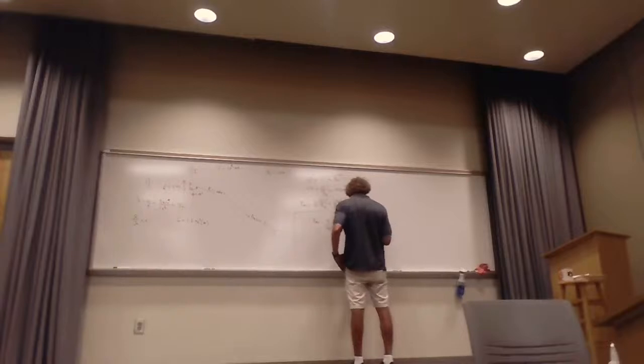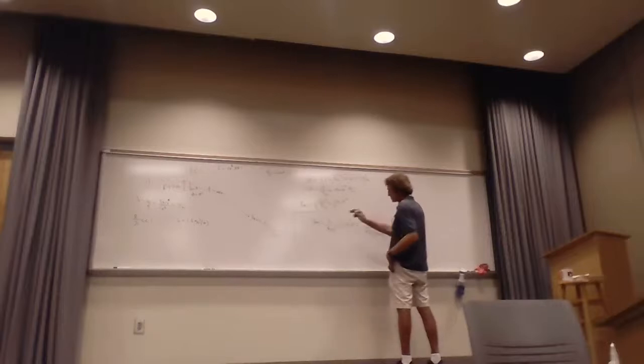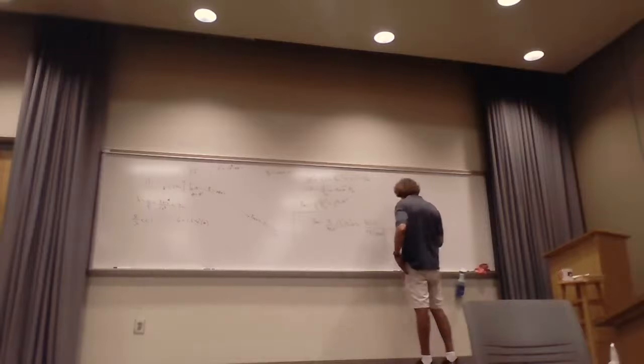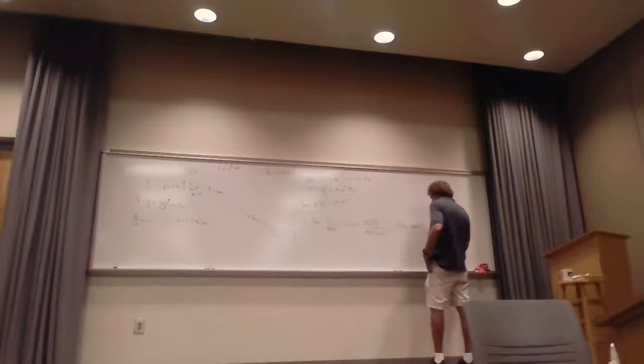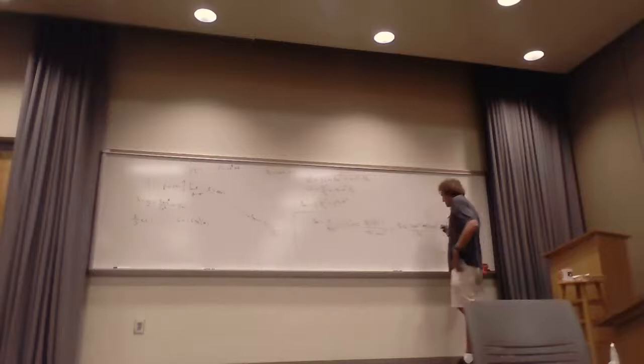4,000 squared. I can go ahead and just inverse solve this, and since P average there was 30 microwatts, I can get P total here equal to P ab, which would be equal to 30 times 10 to the minus 6, times 4 pi times 4,000 squared, divided by 3/4. And when all is said and done, you turn the crank.